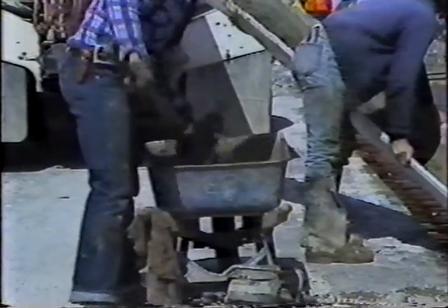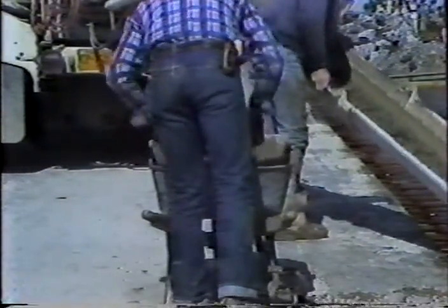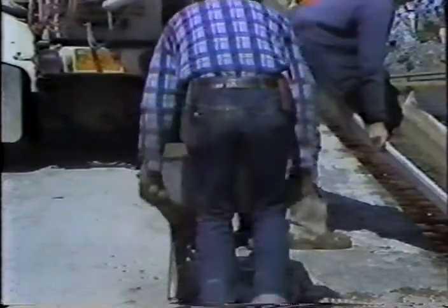The sample should be mixed with a shovel, just enough to give it a uniform appearance. Then it should be covered to protect it from the sun and the wind. Don't let it dry out. One last point in sampling: check the time. You have 15 minutes to run the testing and cast the cylinders, if they're going to be made from this load.